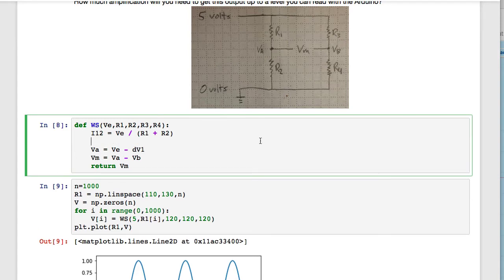Now, if I wanted to get the voltage drop across R1, I'd need to use V equals IR. That's Ohm's law again, just like I is equal to V over R, V is equal to I times R. In this case, I'm looking at the voltage drop across that resistor. The current flowing through R1 and R2, that is the current flowing through R1.